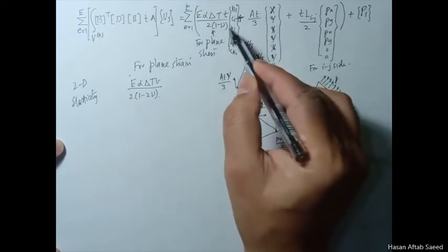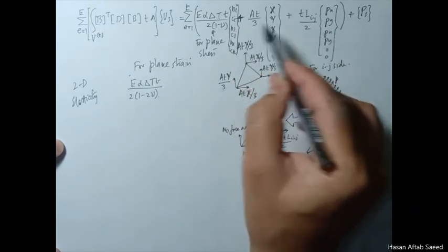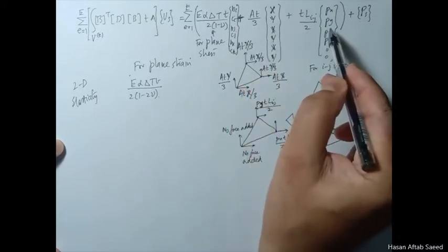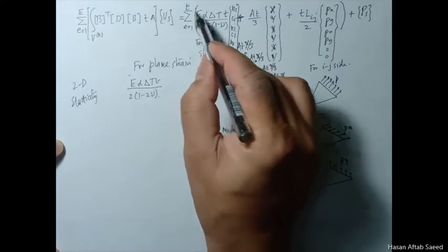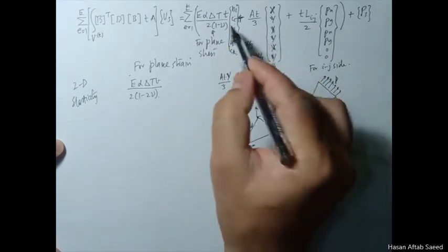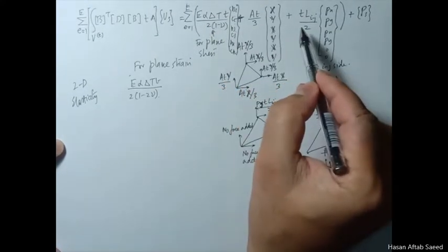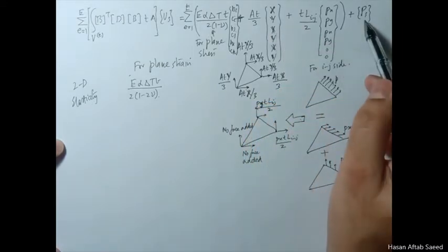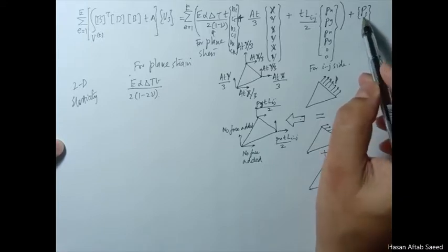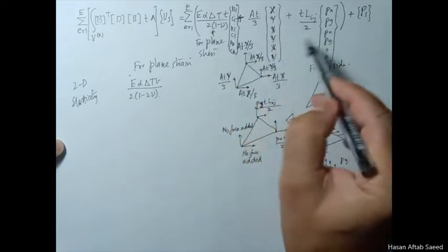All elements have to be dealt with in the same way, and then all have to be assembled again using the connectivity table, and this is where it shows. And once the whole F matrix has been constructed, at the last step the nodal forces, if they are acting anywhere, are added at the end. They are not involved in the summation process.